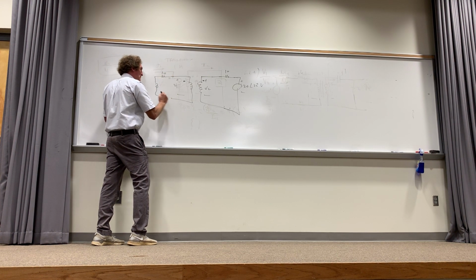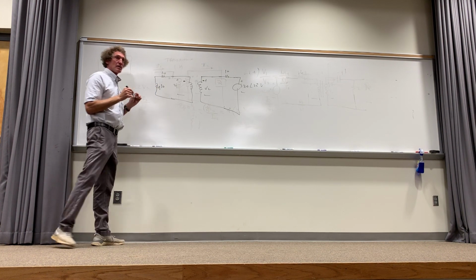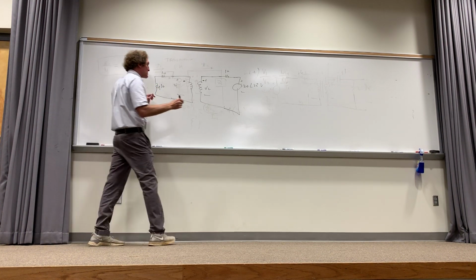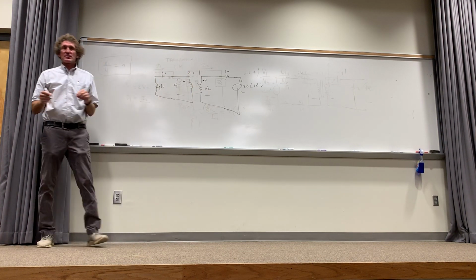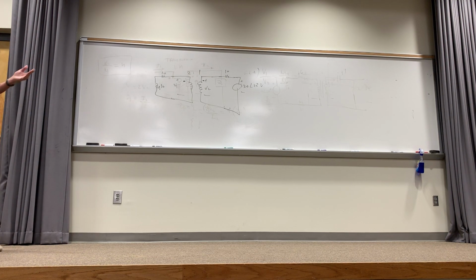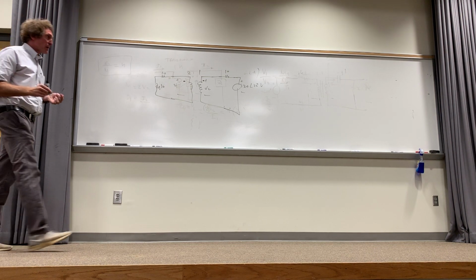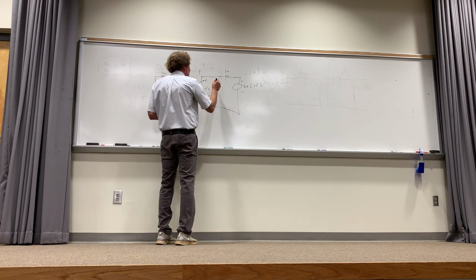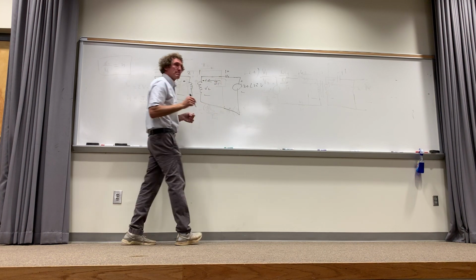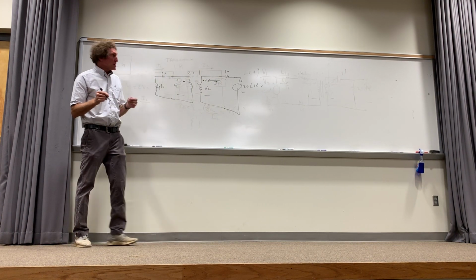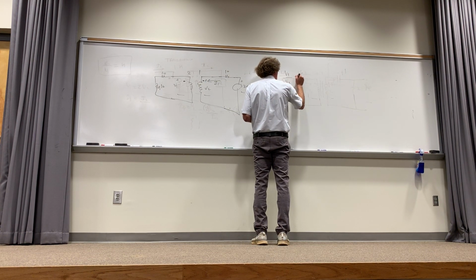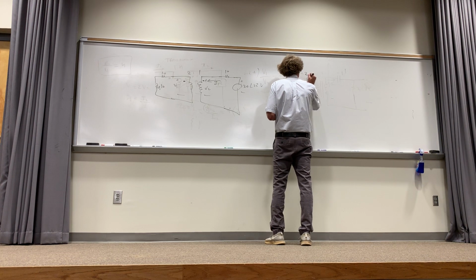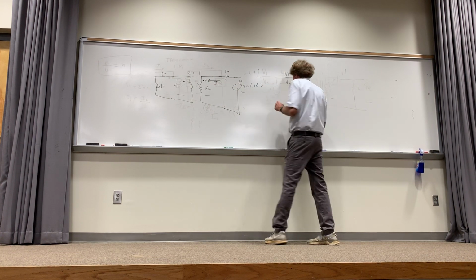10 plus J10. And then I'm going to have a turns ratio of, say, 2 to 1. Now some of you have figured this out by now. I've got the turns ratio, I've got the dots on the terminals, I've labeled V1 and V2. I can label this as I1 if I want, but I don't need to. Now, I know that V1 over V2 is proportional to N1, or 2, over N2, or 1. I know that, right?